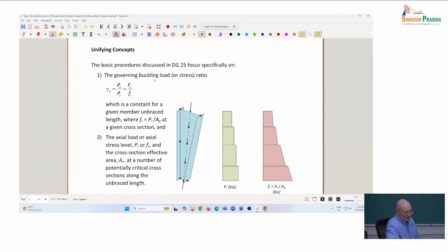Well, given this column, we can model it. Given the tools in Consteel, it's relatively easy to basically create a model of this column. And I can get an elastic buckling eigenvalue, gamma E. And so that's a constant for the whole thing. But now the demand, and so this is written to accommodate either ASD or LRFD. So we have FR as the required stress and PR is the required load, but you can replace those by FU and PU if you wish. That's for LRFD.